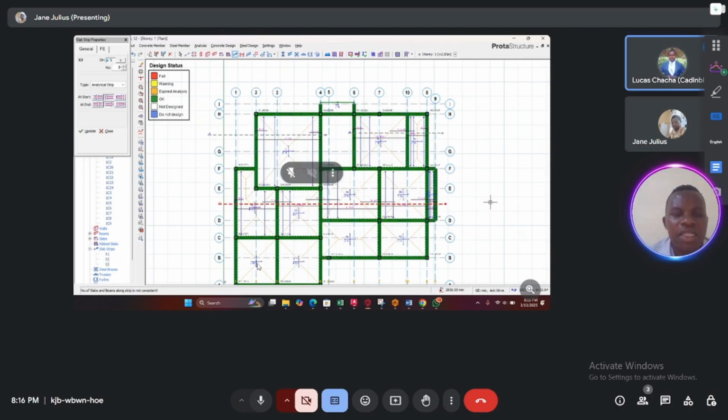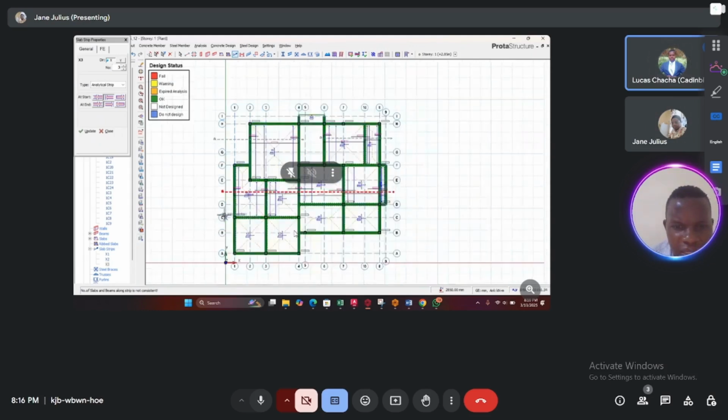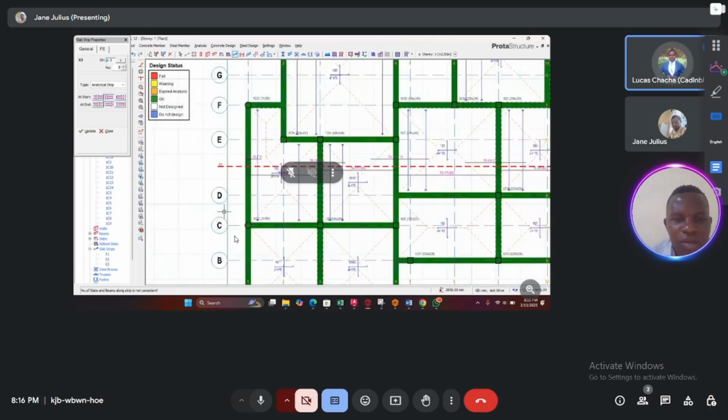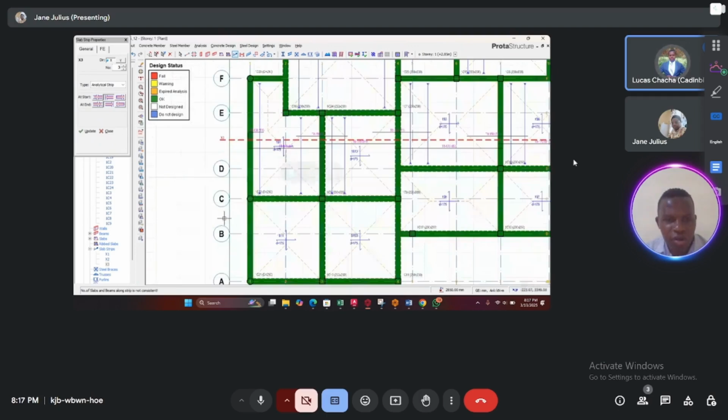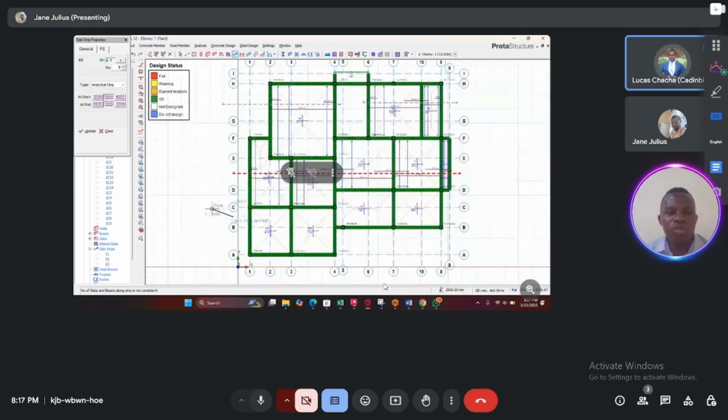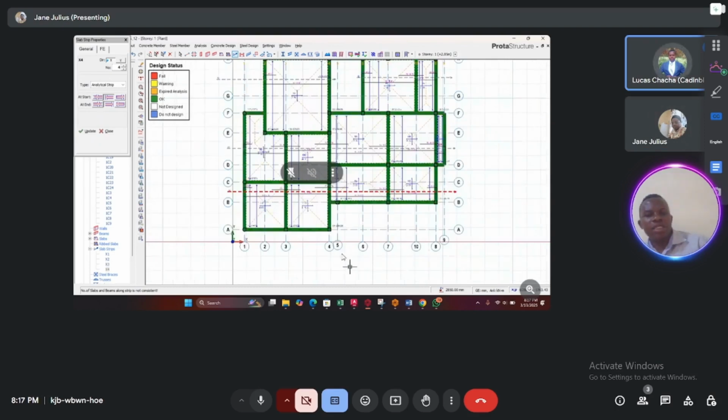Nice, very nice. So let's also click between C and D. And then you try to run it across between C and D. No, not there. We are already done on that. Yes, they want to run across all those slabs. So just be very keen on how you are positioning your strip so that you do minimum strips and then you cover the entire area. Yes, click. Nice. So let's now try to do along the y-axis.